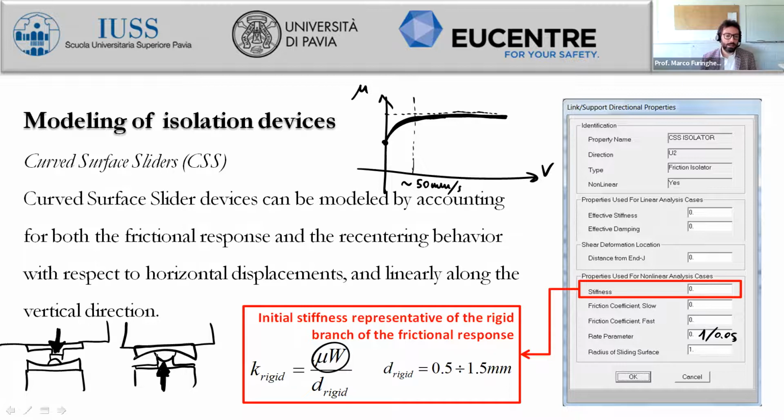Once we have computed this, we can check the maximum displacement during the time series of displacements at the isolation level, and then we can just apply the vertical force times the maximum displacement of the isolator, either to the substructure for the first solution, or to the superstructure for the second solution, as a constant value of additional moment, rather than applying the force at a certain location in order to consider the proper internal stresses and forces induced by that additional force and location.